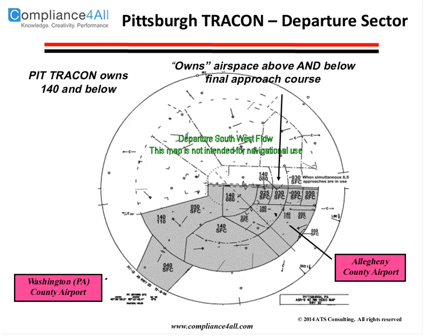You notice in here, this is the airspace that I own as a departure controller. I own surface to 2.5, surface to 3, surface to 5, surface to 5. And over here, I also own 8 to 14 and 8 to 14. Therefore, I own airspace that is beneath and above the final approach course for aircraft landing at the airport. The approach controller owns in between. That's how this airspace is divided to create quarters and little holes I can go through to get airplanes in and out. This airspace configuration is very complicated, but it has evolved over years and years of traffic evolution, trying to squeeze out every single bit of airspace usage that you can.